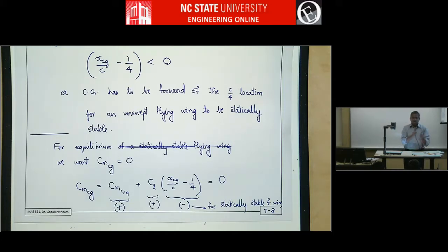The pilot's all the time keeping angle of attack at the desired value. Whereas if it's a very nice and stable airplane, you can take your hands off the control column and do other things, operate radios or look at the map, and the airplane will still be flying at a fairly constant angle of attack.